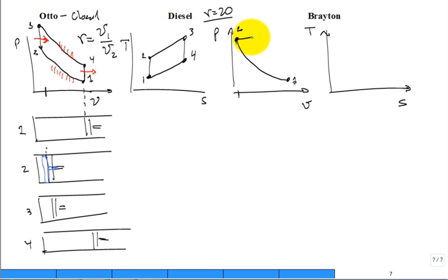In a diesel engine, let me back up a little bit. In a gasoline engine, when you ingest air into the cylinder, piston cylinder, is the fuel mixed with the air? It is. When did it get mixed in the air? In the intake manifold. Or with the fuel injector right before it goes into the cylinder. Somewhere in the intake system, okay?